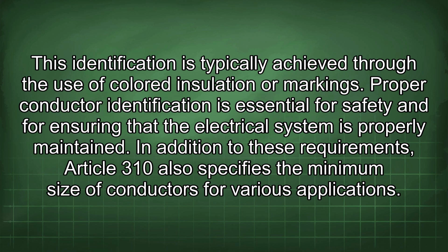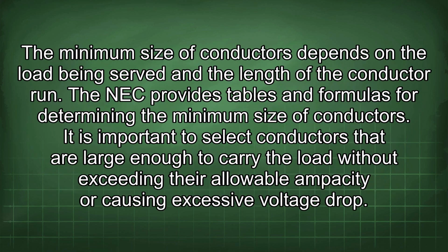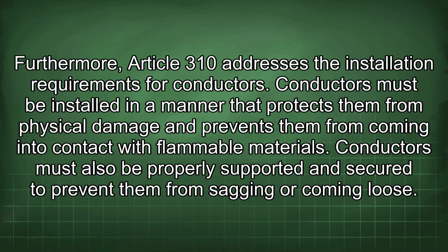In addition to these requirements, Article 310 also specifies the minimum size of conductors for various applications. The minimum size of conductors depends on the load being served and the length of the conductor run. The NEC provides tables and formulas for determining the minimum size of conductors. It is important to select conductors that are large enough to carry the load without exceeding their allowable ampacity or causing excessive voltage drop.